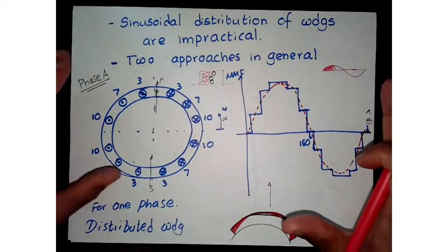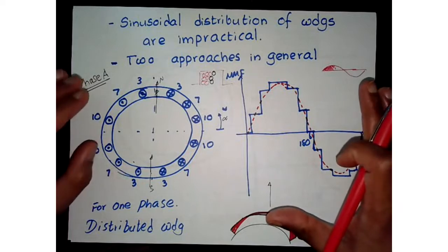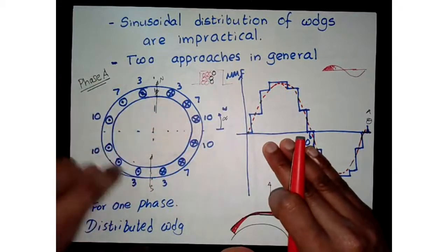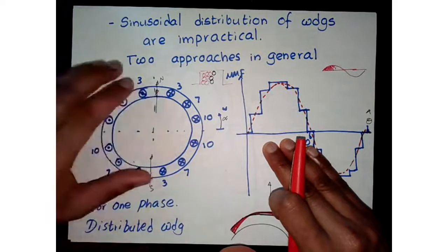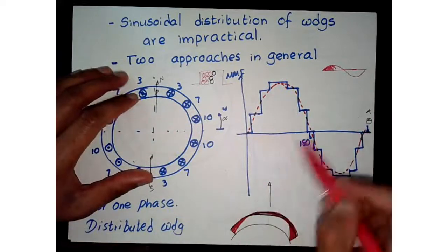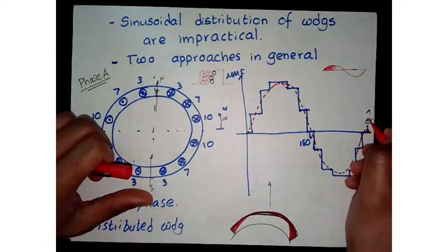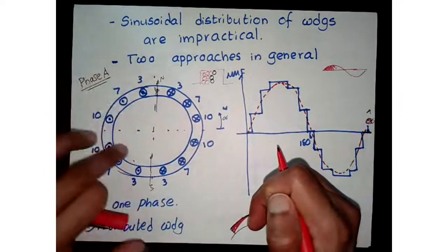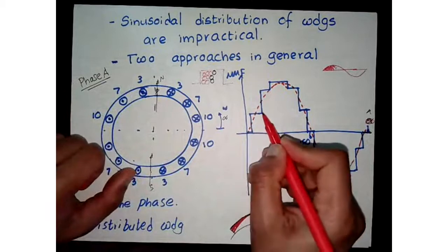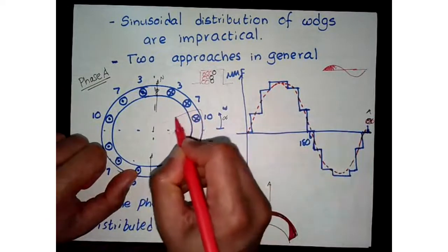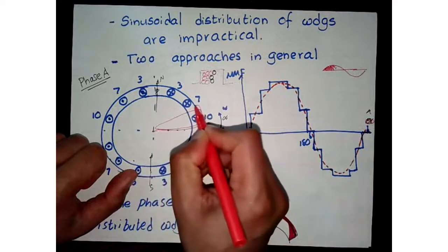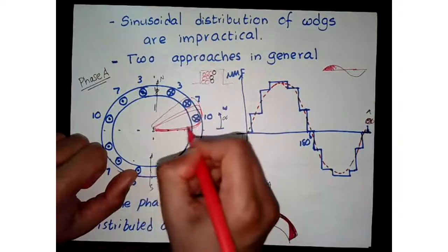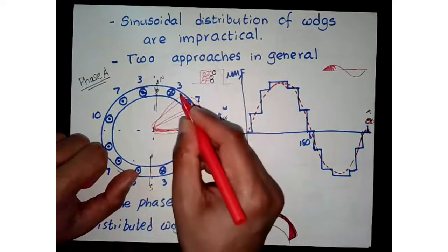And if you're sticking to phase A, and if we look at the MMF plot, magnetomotive force plot, using our Ampere's law or flux, by counting the number of flux lines, you can see that with changing alpha, as you go around the machine, we see discrete variations, because depending on where we consider our loop to be at, we'll see a jump in the number of conductors, and then it'll stay like that, and then we'll see another jump here.